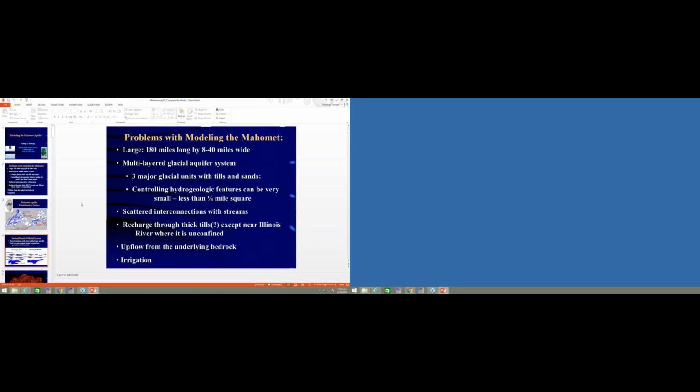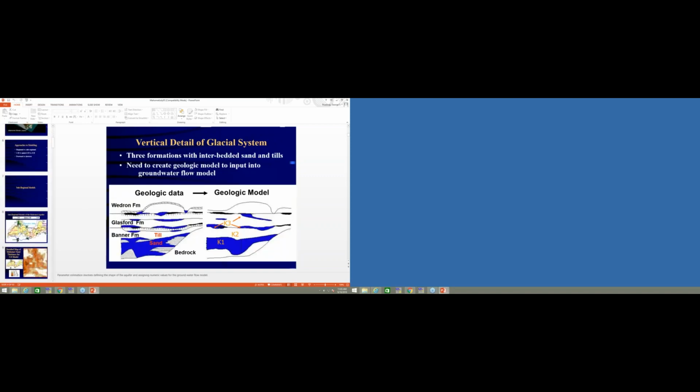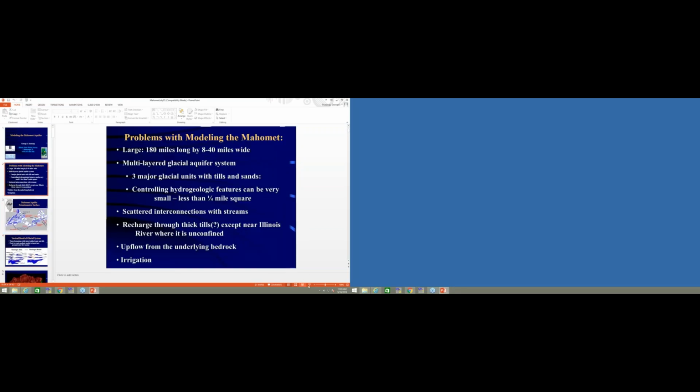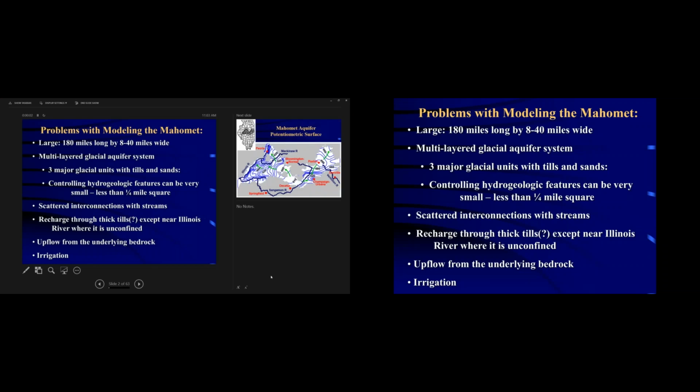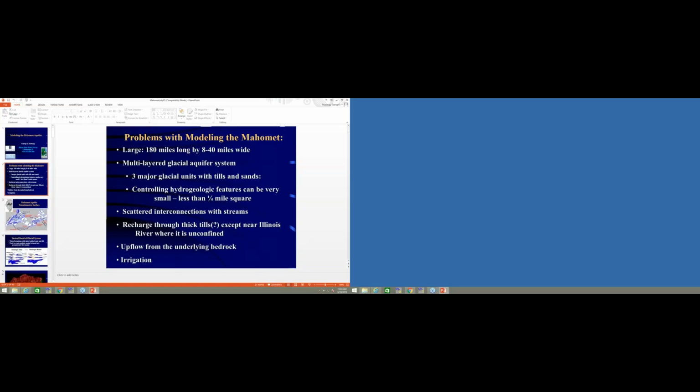Yeah, because I've talked to Daniel about this, but essentially my long-term goal with the whole dewatering project is, I don't know about showing you any of the hydrographs, but it's just peak and valley, just because of the manual switching on and off of pumps. So if we could keep a pretty even hydrograph, where we just have a target elevation in each area and try to keep it there, rather than, oh shit, it's above it, turn the pumps on; okay, it's below it, turn them off. So that's something to keep in mind.